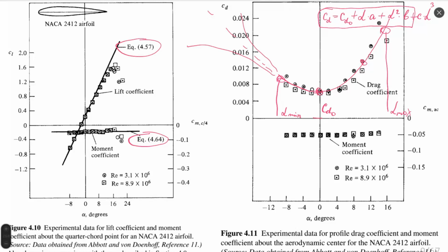If you know the limits and have points in the middle, you can use this function with no huge problem, because definitely your function will not have a local extremum where we have no experimental data. This function has its minimum in the middle and has 2 extremums at negative and positive angles of attack, right? It has 1 minimum and two maximum values.